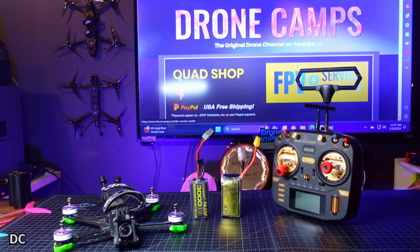Now, if you're flying something like the Nazgul Evoque, what you see on the bench here in front of you, this one can fly on a LiPo, but it's not going to be flying on something like a Li-ion. You're not going to fly a Li-ion on an FPV freestyle drone. So it's very important that you not try to fly a Li-ion on a high amp draw type of quad. I say high amp draw because even though these are low kV motors, they're still above 2000 kV. They are meant for 6S, but a Li-ion will get destroyed on an FPV freestyle drone. So that's very critical.